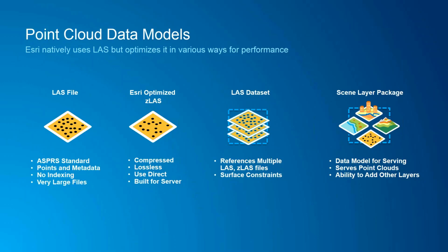But where the LAS data set comes in really powerful is when you have multiple different LAS files that you want to work with kind of seamlessly. And so the LAS data set is still critical to kind of create these virtual mosaics of point cloud files themselves. We also understand that some of these data sets get extremely large. People have limitations on how much storage they have. So we also implemented this open standard called ZLAS, which does provide some compression to push those file sizes down. It's not required, but it's available to you if you want to take advantage of it.